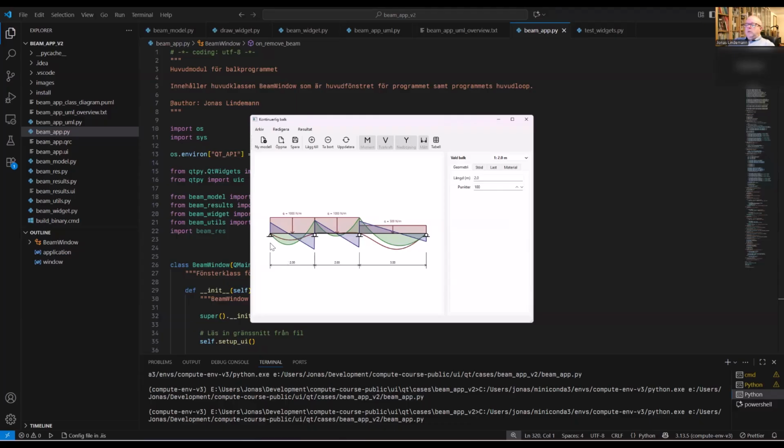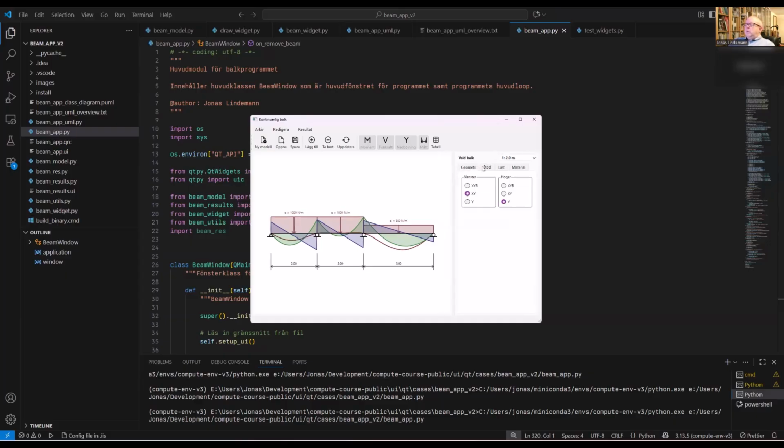That is a beam that is fixed on different supports like this. So you have a fixed support which can rotate, and then you have a 2-meter beam here, and then we have a rotating fixed support here that can move in the X direction. It displays the deflection of the beam, the section forces and the moment in the beam, and it will also visualize the loads. On the left side, you have a tabbed interface for the different parameters.